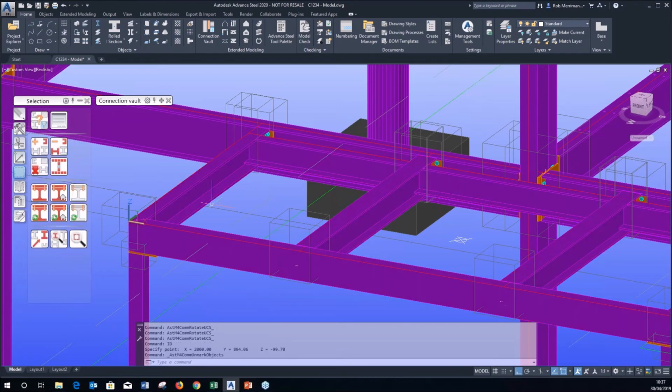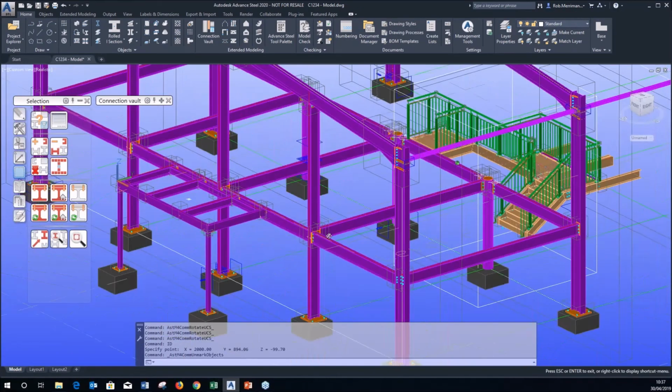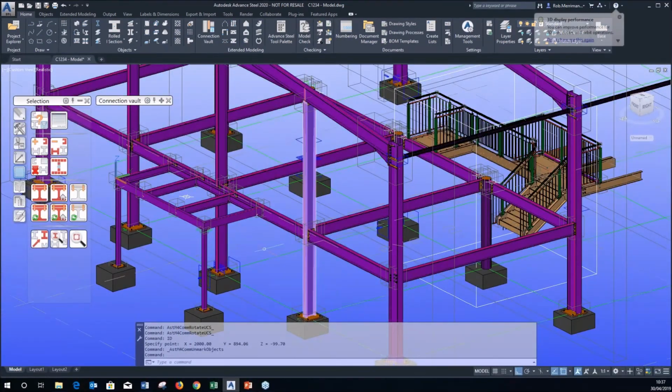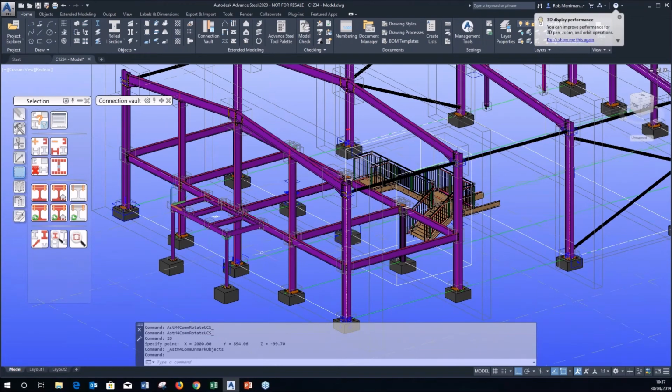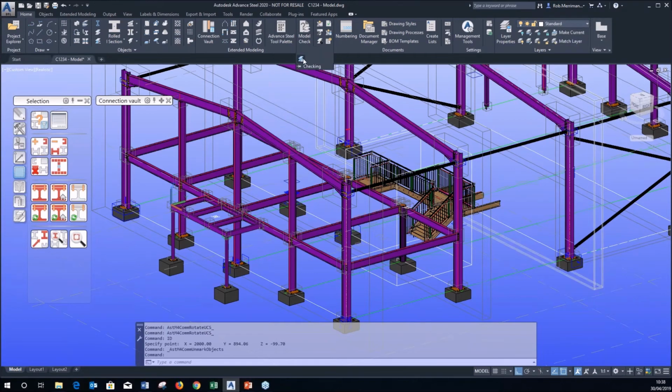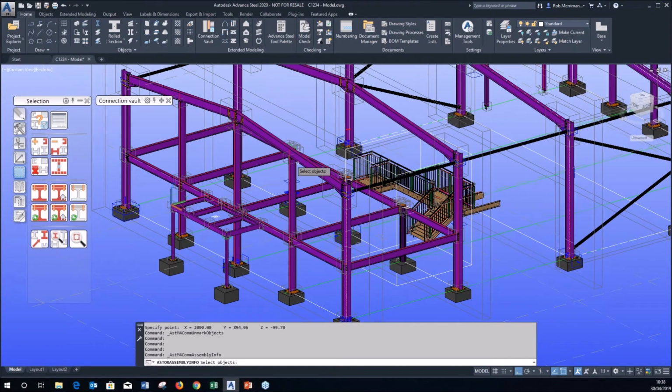So there's just an extra little tip there for you if you ever need the center of gravity or total weight. Maybe you're doing balustrade panels and you're concerned about the weight because they're being manually handled. That's a very good little tool. There's also, if you click the drop down, the assembly weight information.